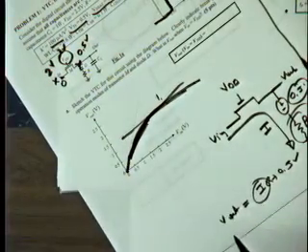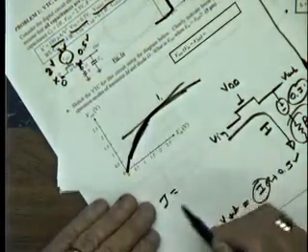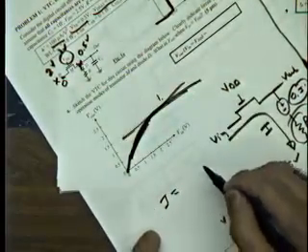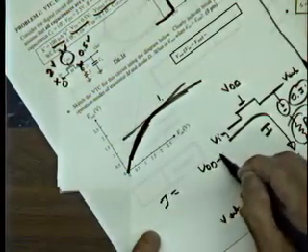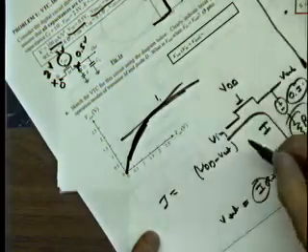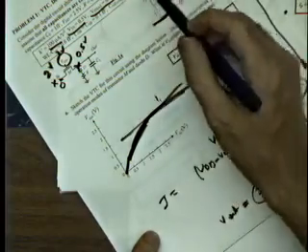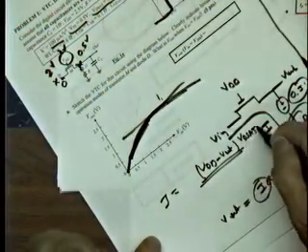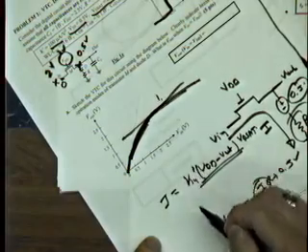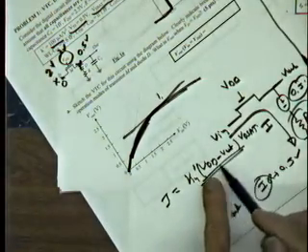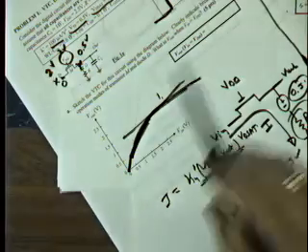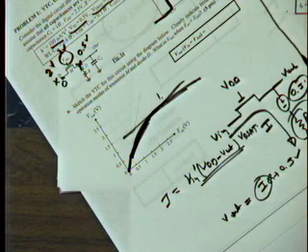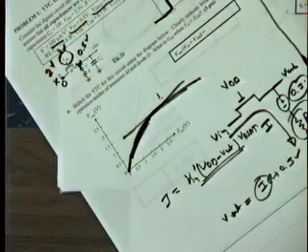Because the I of this device is going to be determined by VGS. You have to look at the operational mode of your transistor here. But it's going to be equal to VDD minus V out. And if it's a long channel device, or what, I think it's a long channel device. No, it's a short channel device. So we can use the VD sat times Kn prime type of equation. So you can see that your current is going to be a function of the output voltage. That's really what you're pointing to. That is correct.